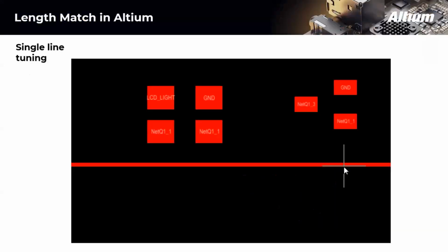Now, let's look at length matching in Altium Designer. I have discussed differential pairs, and you might be knowing about length matching as well. We mentioned earlier that the logic value of a differential pair is determined by the difference between the two voltages. Due to this behavior, we want our signal pair to arrive at the destination at the same time. The receiver might allow some difference, called skew, and the skew can be found in the chip datasheet, but ideally, we would like our signals to arrive at exactly the same time and avoid any skew altogether. To avoid this, we have the ability to tune our signals so they arrive exactly when they should.